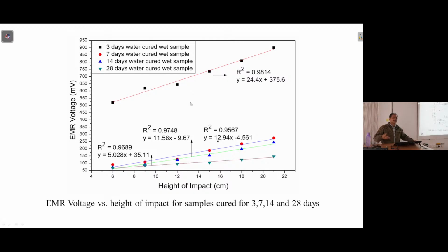At least for 14 days they are kept as such, and thereafter you proceed further, because it takes time to attain the strength, any cement based structure. That is because this reaction takes a longer time. So effectively, as that continues to occur, it gains strength.